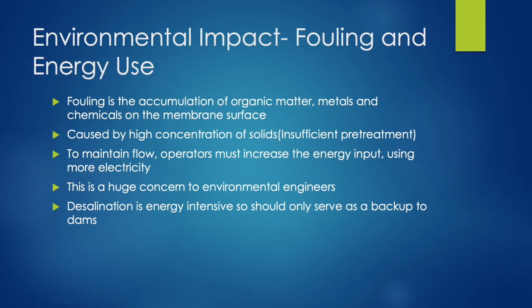Fouling is the accumulation of materials on the membrane and decreases the effectiveness of reverse osmosis. To maintain the same flow, engineers must increase the energy input, using more electricity. This again increases the toll on the environment and also increases costs.